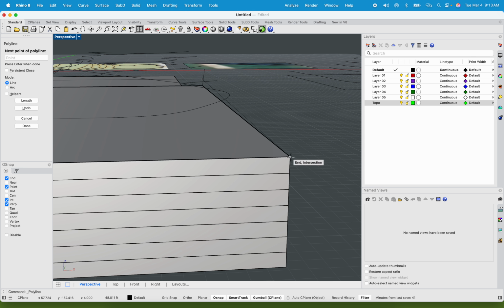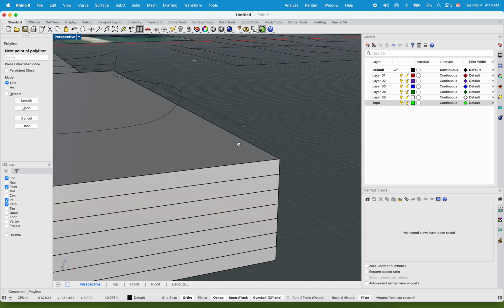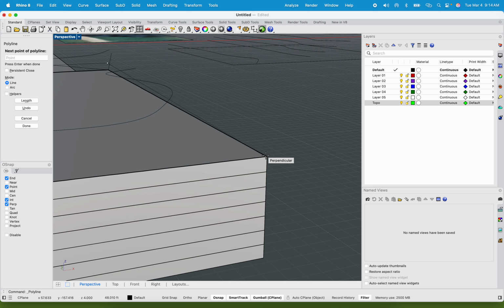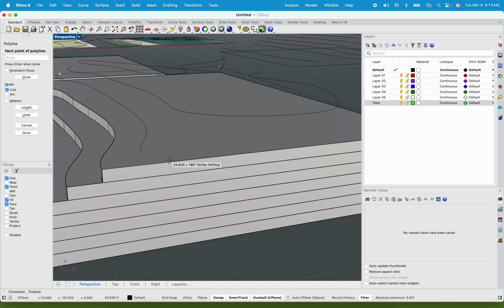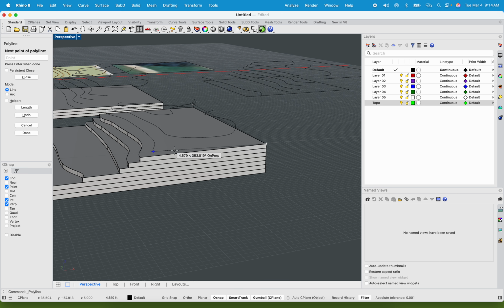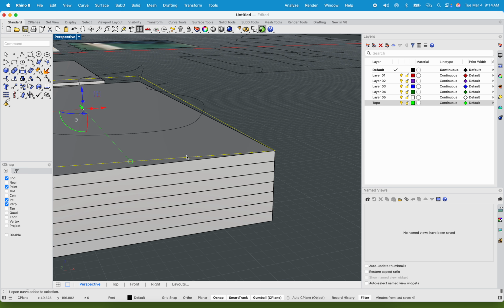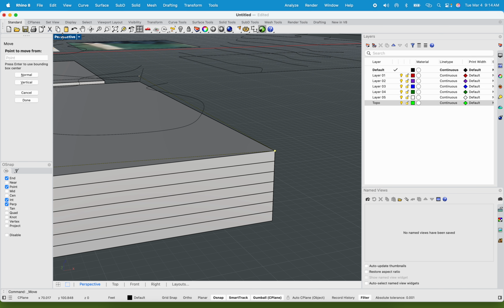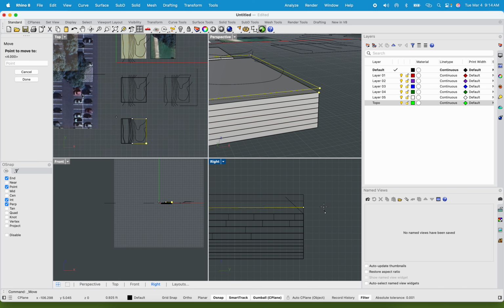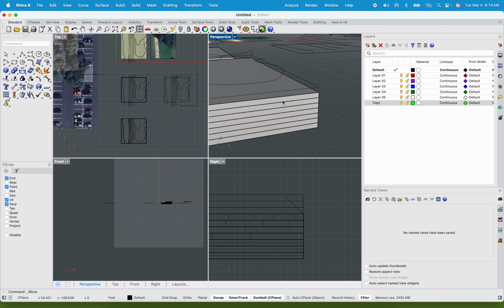So technically, I guess this could be drawn in 3 dimensions. Not exactly easy though, as you can see. It doesn't really know how to lock onto an intersection point. So be careful. When in doubt, just choose that point that you know. That way you can lift it up 12 inches. See what it did there? Anyway, we're learning all kinds of stuff today, or at least how we would actually fix some of our errors, which to be fair is probably more important than just getting it right every time. But 12 inches, enter, straight, sweet.